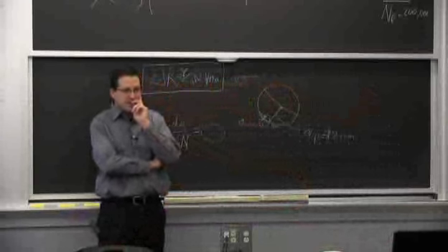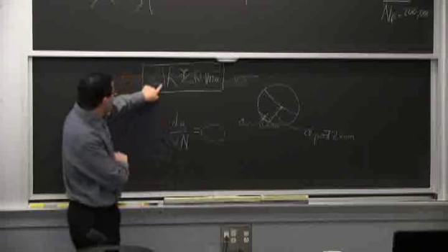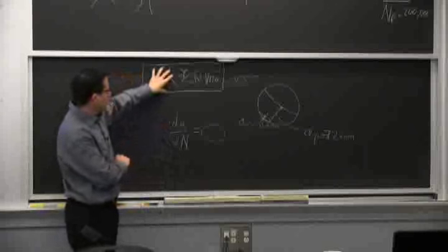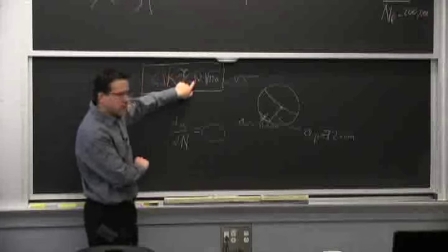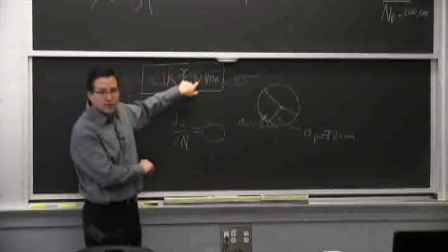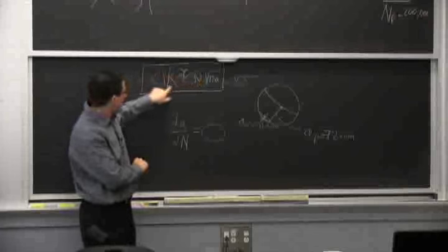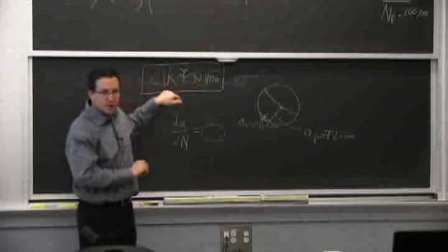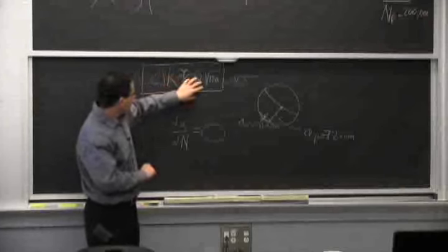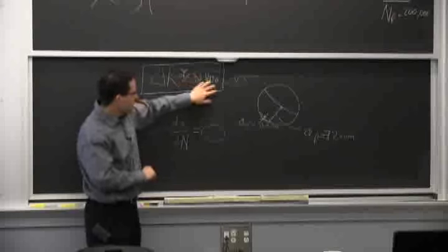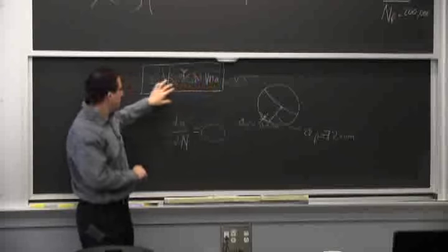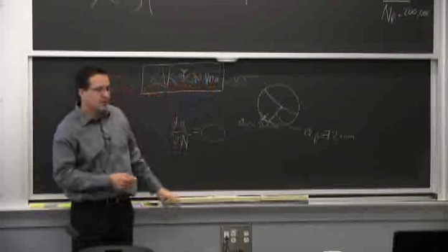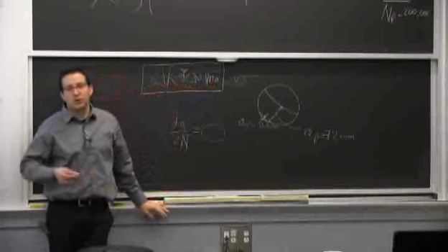So this is a curve that tells us for a certain value of the demand, right? All of this here from our previous class on fracture mechanics is the demand for a certain stress. In this case, a stress range. I just put a delta and a delta here. Otherwise, it's the same thing we've talked about. For a certain range in stress and crack length, this is the extent of the demand to grow the crack.